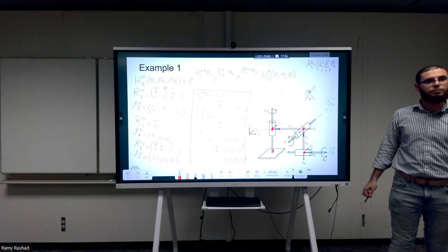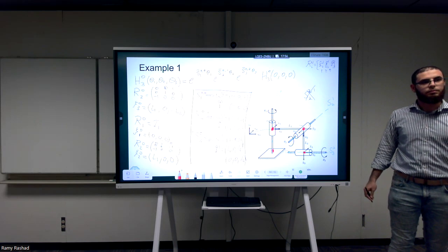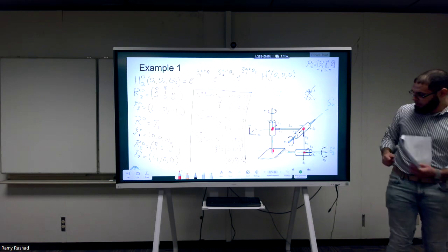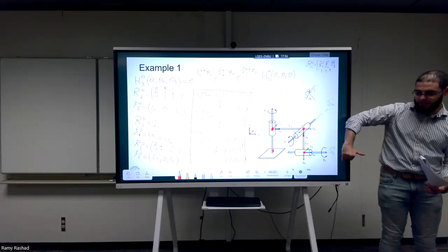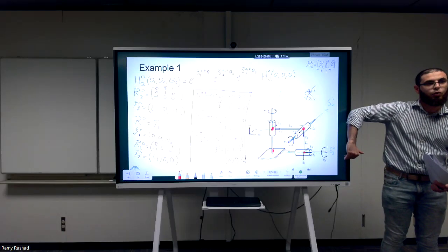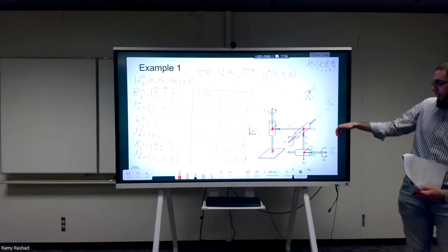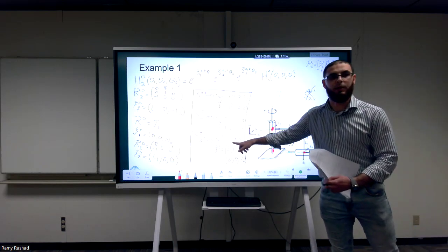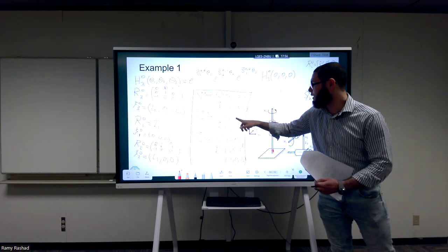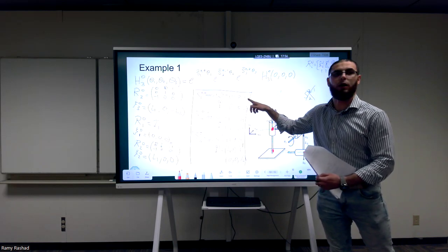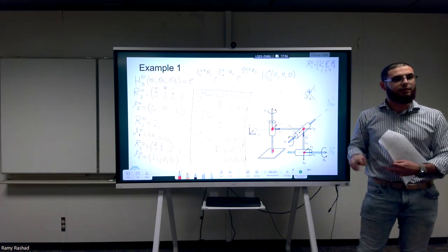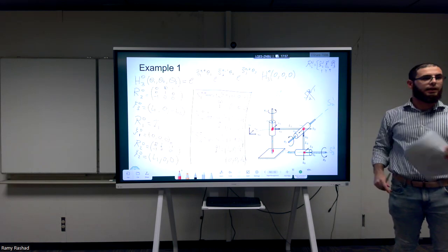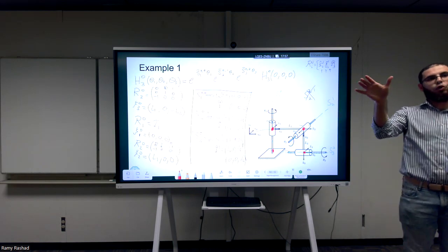Will it be affected by clockwise and counterclockwise rotation? Yeah, it affects, because here for theta 3, this is the positive axis about it. So we have to take this into account. If I was rotating theta 3 like that, then this direction would have been -1, not +1. So here, for example, you see this is 1, 0, 0, this is 0, -1, 0, and this is 0, 0, 1. So the convention you choose for theta plays a role here in the axis. The axis has to be according to the right-hand rule.